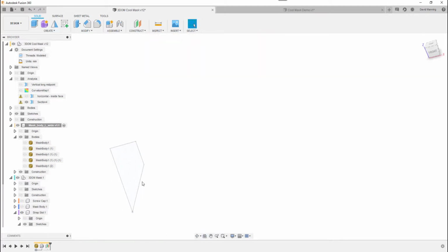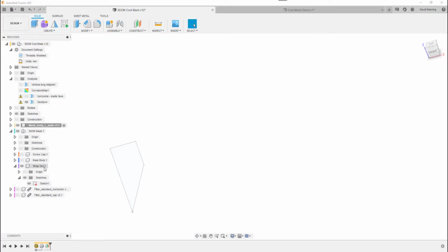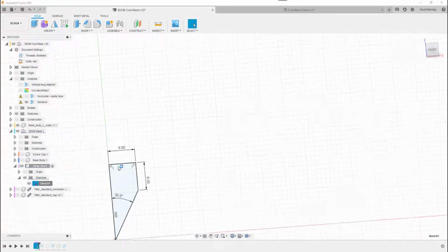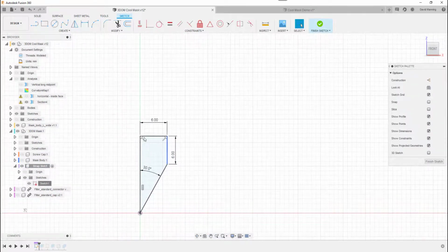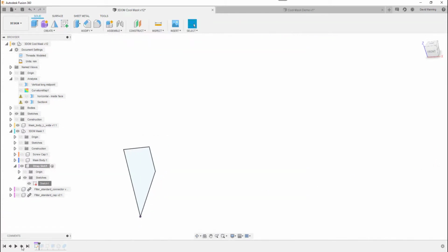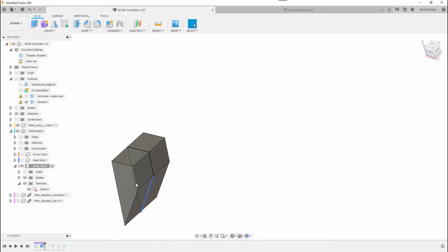Now I want to 3D print these, so obviously we need to have this angle here, let's go back down to there, be greater than 45 degrees. I've picked a fairly high angle, and to be honest, I did check that when I'd mounted it properly where I wanted it on the mask, and came back in here to edit the sketch. Great way to deal with that. So in the edit sketch, I've made it 30 degrees, 6mm by 6mm, and what that allows me to do then is just extrude that again to a measurement that I defined.